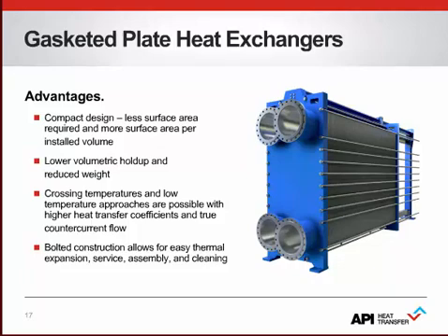As the plates are held in place by so-called carrying bars and tie rods, it is easy to assemble and disassemble the heat exchanger on site. Furthermore, you can add or remove plates in your application. By transforming the flow arrangement internally, you can set new configurations in an existing plate heat exchanger. Nothing is welded here that would require welding work to put a new configuration in place.